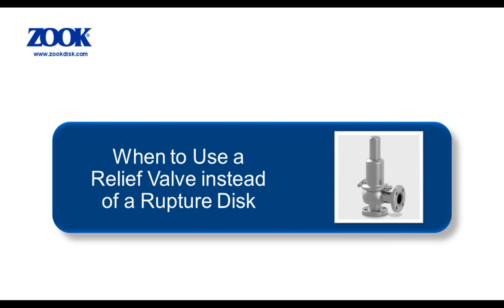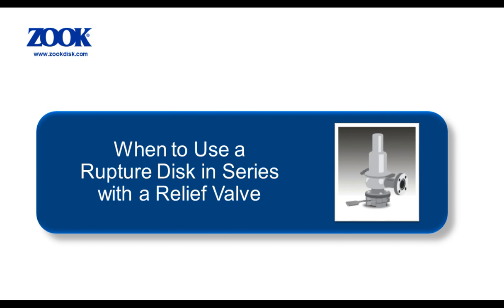Notwithstanding the benefits of the disc, there are many cases where a relief valve is actually the preferred method of pressure relief, and we're the first to acknowledge this. The most common would be in processing or continuous service applications where downtime is a problem. A valve will typically reclose after relief, whereas a rupture disc would need to be replaced prior to a restart. There is a way to get the benefits of both the disc and the valve.